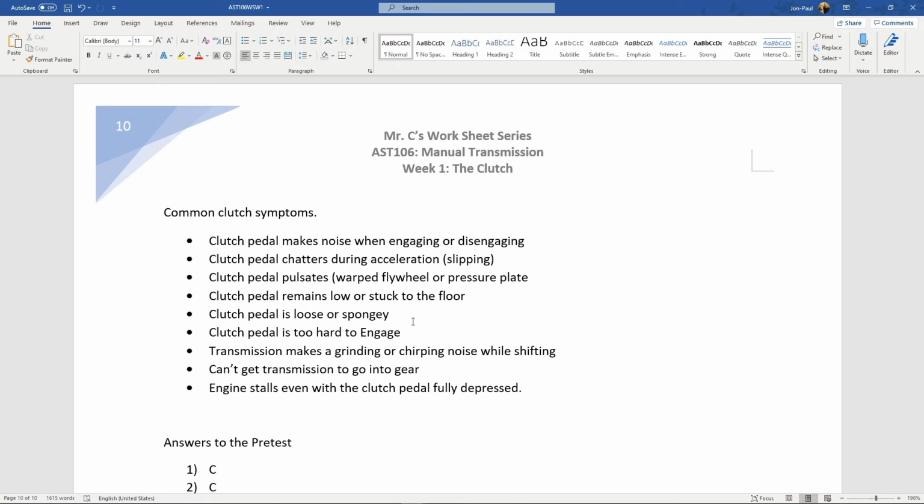If it's under the vehicle, so it's a rear-wheel drive vehicle, put it on a lift and have, who was it, Bill? It was Travis. It was Steve. Who's my porter? Jose, come get in this vehicle. I'm going to put you on the lift. Push the clutch pedal up and down, up and down. Now I'm going to get under it and watch it.